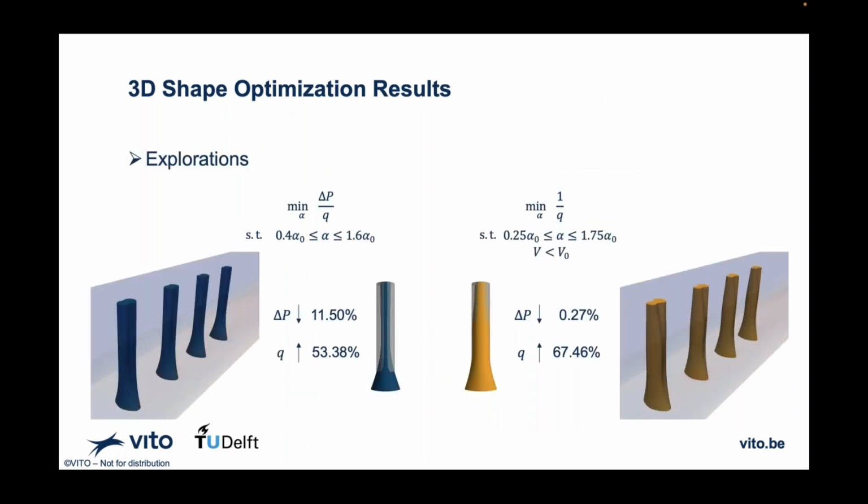Actually, the problem that I face is that the flow equation diverges, and then of course I couldn't go for the adjoint. But there may also be some cases where the flow equations converge but the adjoint equations diverge because of poor mesh quality or large deformation. Those are the main limitations, in terms of mesh quality.